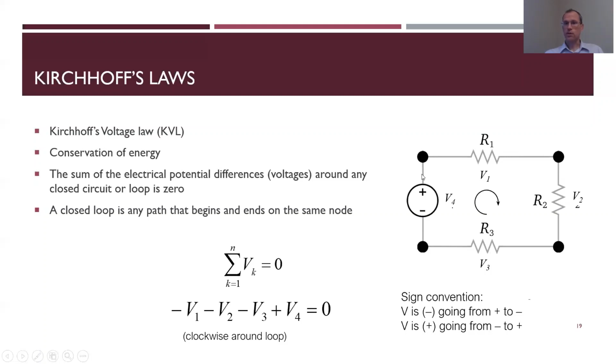So I have 12 volts coming out. This takes up a certain amount. That takes up a certain amount. That takes up a certain amount. Those 3 numbers have to add up to 12 so that it gets back to 0 on the negative side.